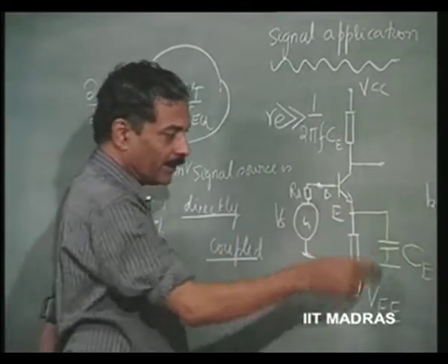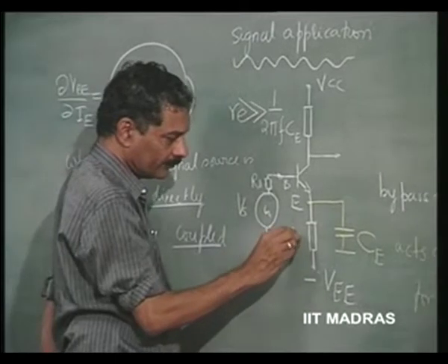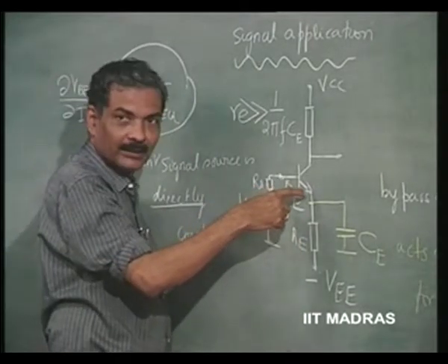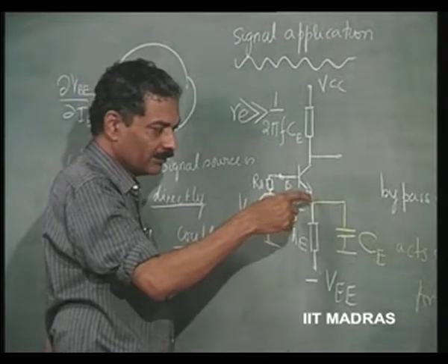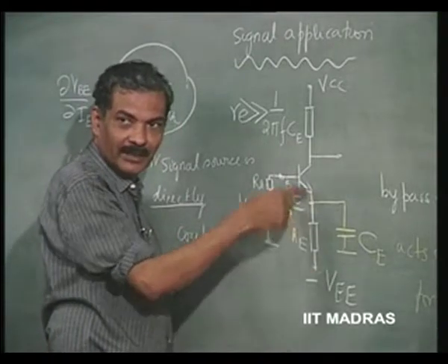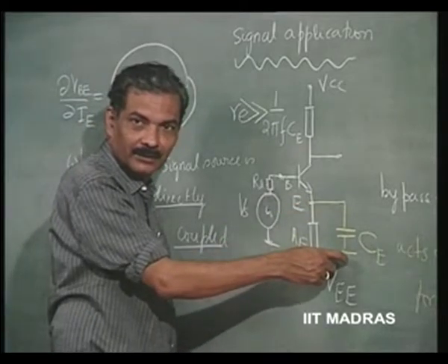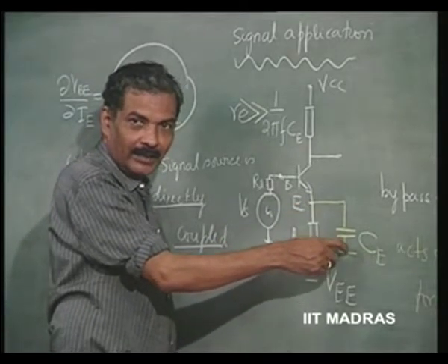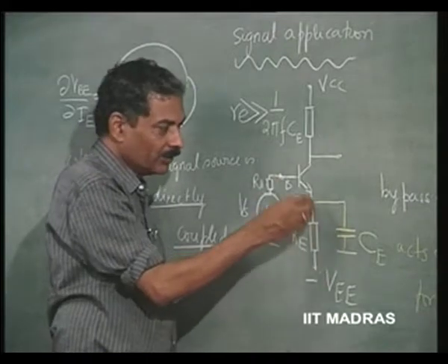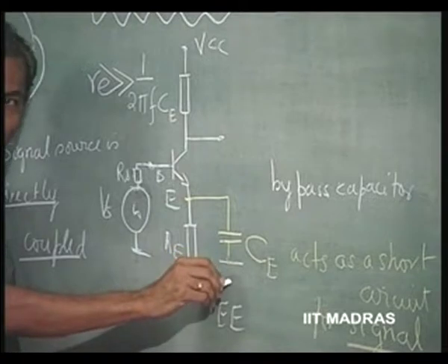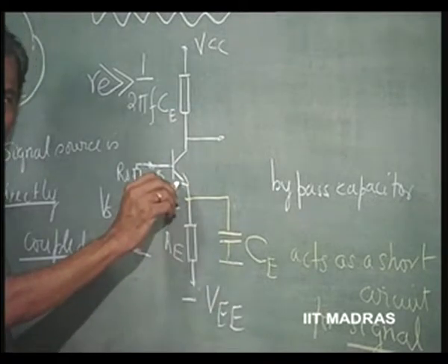So, the bypass capacitor, please remember, is bypassing what? This path which the current would have taken. The current now takes this path, right? And the current is going to be determined mostly by the impedance re, because the reactance is negligible compared to it.